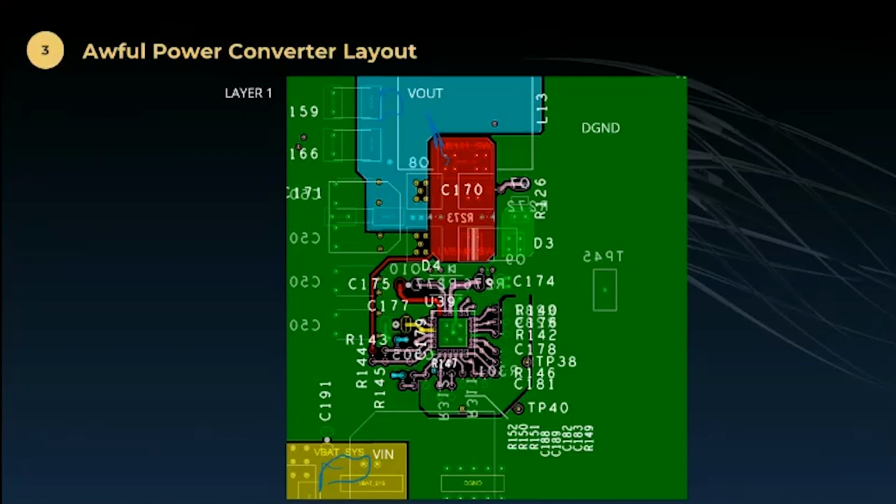If we look for the switches, you can kind of see the outline of the switches, which are on the other side of the board, but the node couldn't have been much smaller than that. But the big mistake was getting it right next to V out, because now that electric field coupling from the switching node to the V out is very strong. And so they haven't properly kept that switching node away from the other circuitry on layer one.